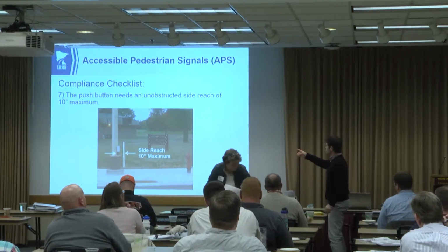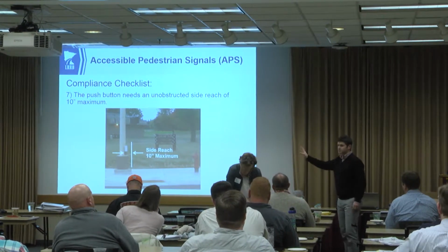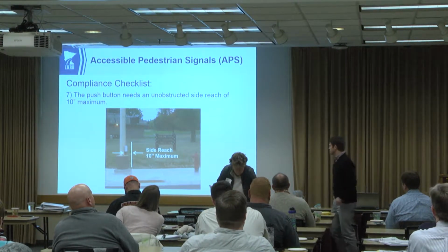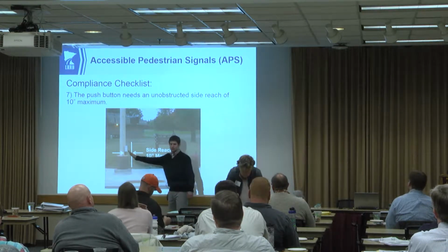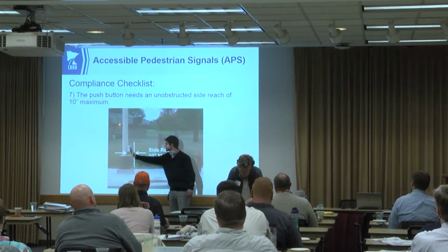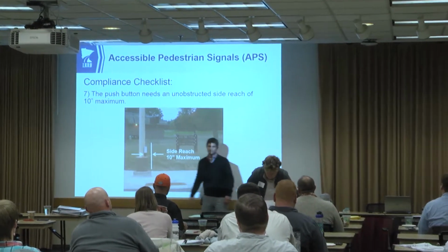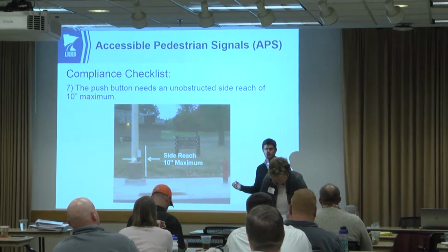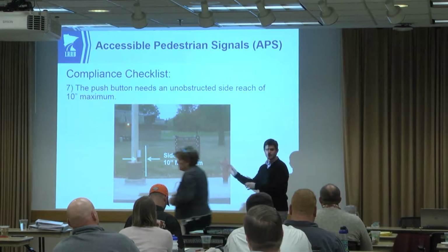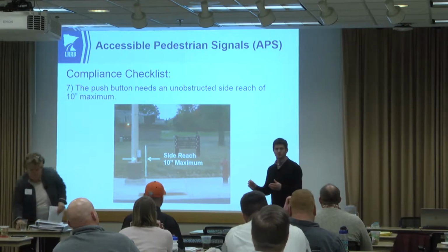Now, if you see a push button on an existing traffic signal pole, based on the foundation size, you're probably already exceeding that 10-inch maximum from the face to where your landing might extend to. One option is to move the pole. Another one is to create a pedestal and put that on. Probably the better option is to get one of these